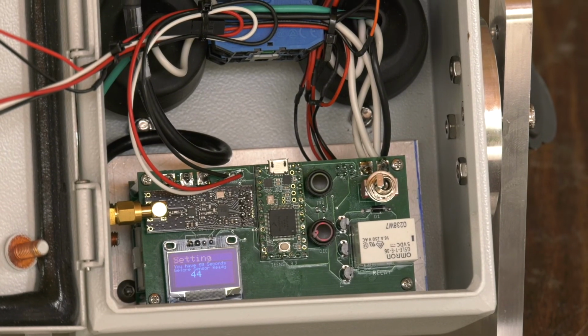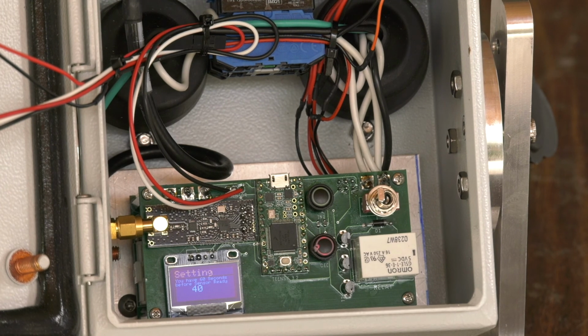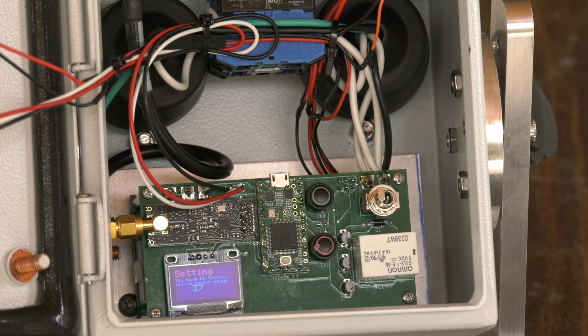There is also a timer included as an internal component communicating with the PIR sensor in its unit. The PIR sensor will indicate if another sensor is activated to the timer. When this occurs, the timer begins a 5-minute deactivation period of its own PIR sensor to ensure that only one enrichment device can be activated at a time. The other sensors will not prompt their timers to relay power to their attached enrichment devices.